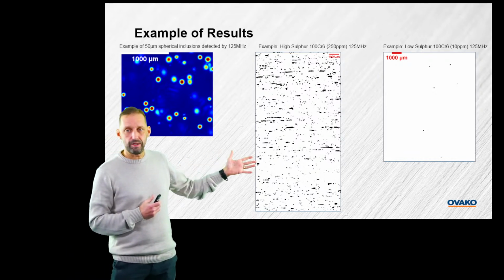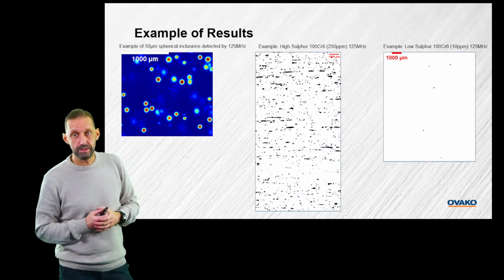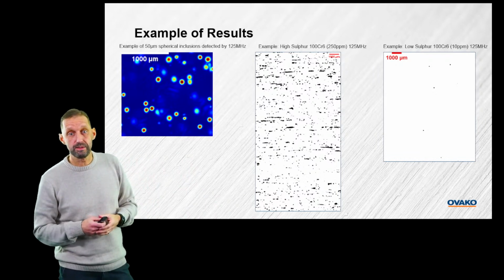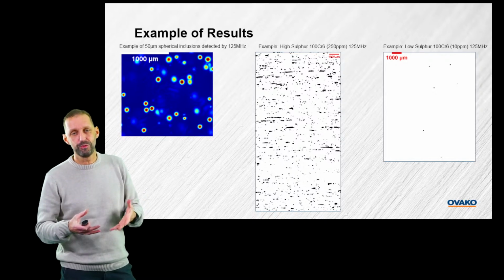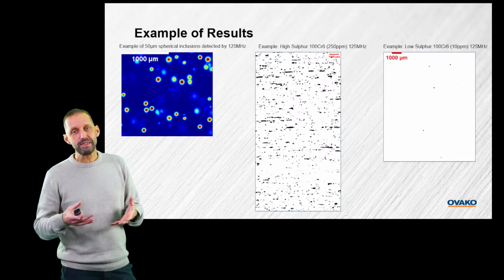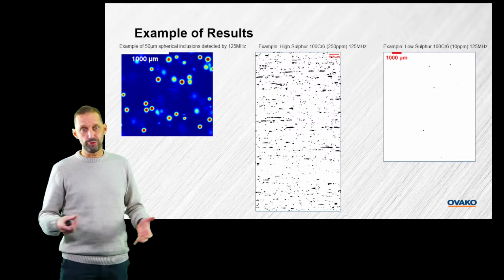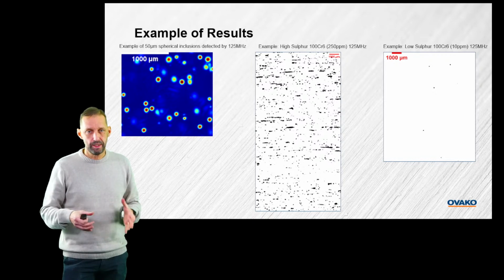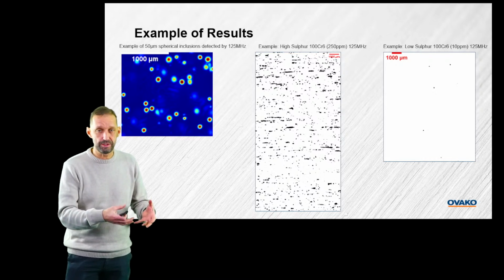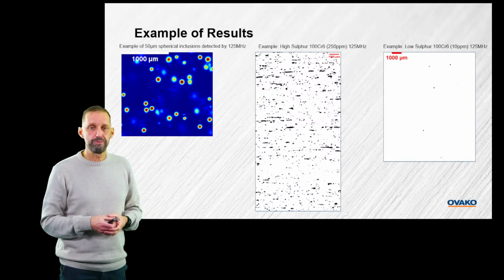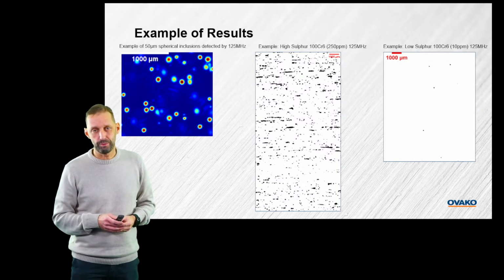But you can also see sulfides, as you see here. It's a comparison between a sulfurized steel and a non-sulfurized steel, 52100, 100 chromium 6 steel, which is both good and bad. We want to quantify, but the problem is you cannot see on the ultrasonic if it is a sulfide or an oxide. So you have to put them together, and that's also a challenge. We also have to work with understanding the sulfur content, how much sulfide we have. So it's something good, but it can also cause some difficulties.